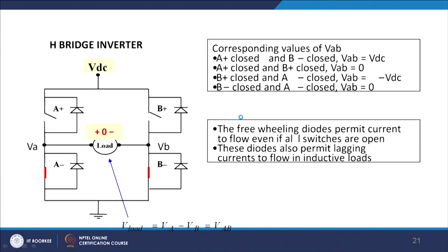So, how can we realize this SPST switch? We have seen it for the DC converter. Let us see how we can do the same thing for the inverter application. So, this is the application. This is a load and the voltage is 0. This is basically A and B. A blocks, B blocks and C closes. So, the voltage across it will be basically 0. The lower 2 switches have been closed, so you are getting 0 voltage.